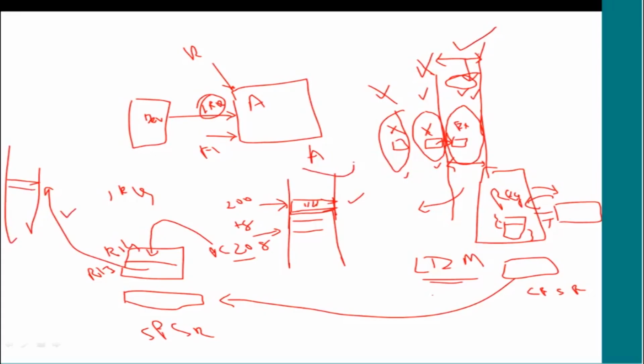The processor could be in ARM state or in Thumb state when this interrupt was generated. It may be executing an ARM instruction or a Thumb instruction. But remember that interrupt handling is done only in ARM state. So if it is in Thumb state, it will change to ARM state.